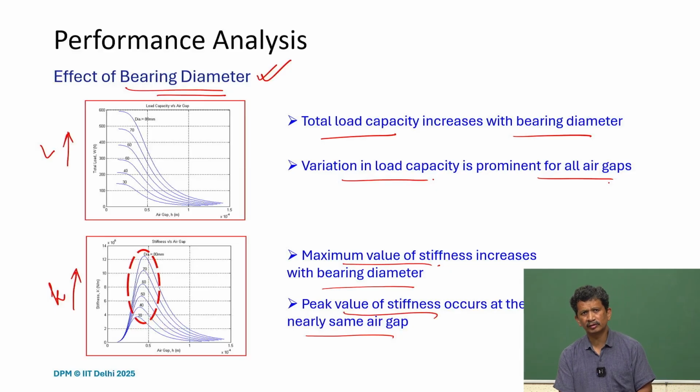But we also need to understand that, like in the case of supply pressure, is it possible to increase it further? There are other kinds of problems, and they are mainly related to fluid dynamics. As we increase the pressure, these elements or bearings are prone to instability, usually called pneumatic hammer, and this is mainly because of the squeeze film damping effect.